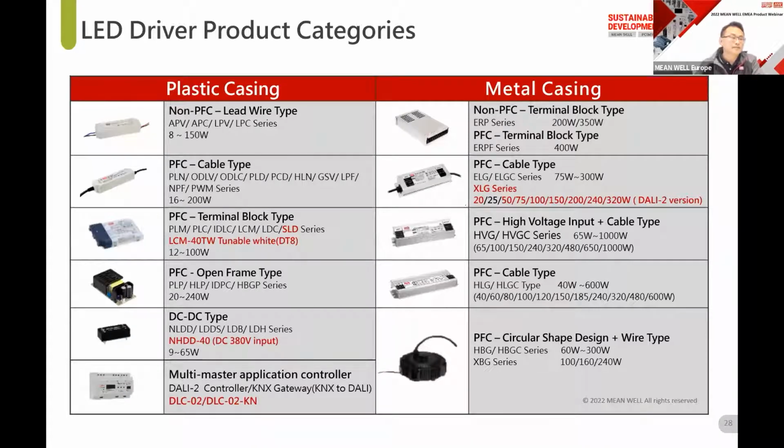Next category is LED drivers. Left side is a plastic casing and right-hand side is a metal casing. I would like to point out the new models in red. LCM40TW Tunable-White complies with the D4i standard. It has a very low minimum dimming level down to 0.2%.